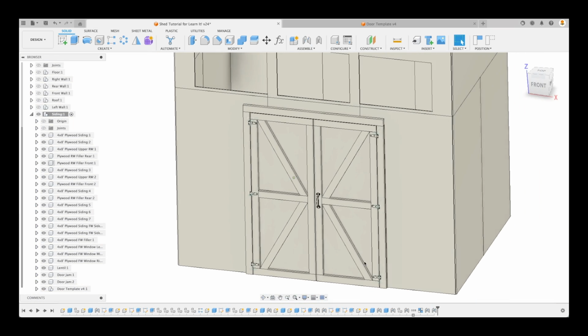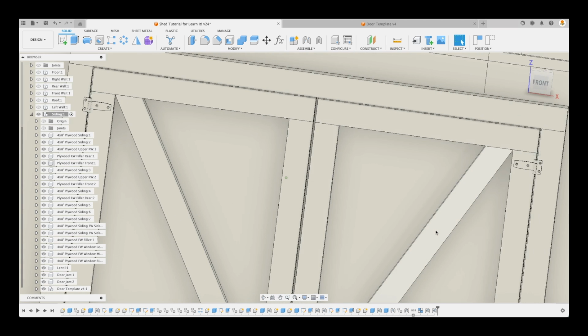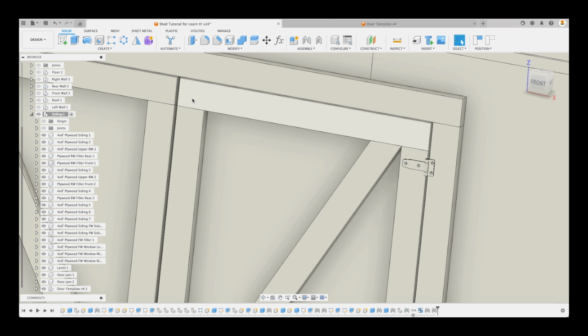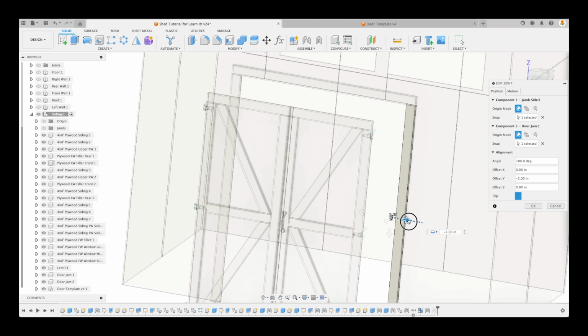There we go. Our doors are in the right location, but I believe the gap is probably off. And you can see it here. The gap here is smaller than the mid gap, and that's because we based it off of the hinge and we don't know the exact hinge dimension. But here you can see it's 0.216. So if I move it over 34 thou, it should be just tickety-boo. So let's move this on over, and we're going to call it minus 34 thou.